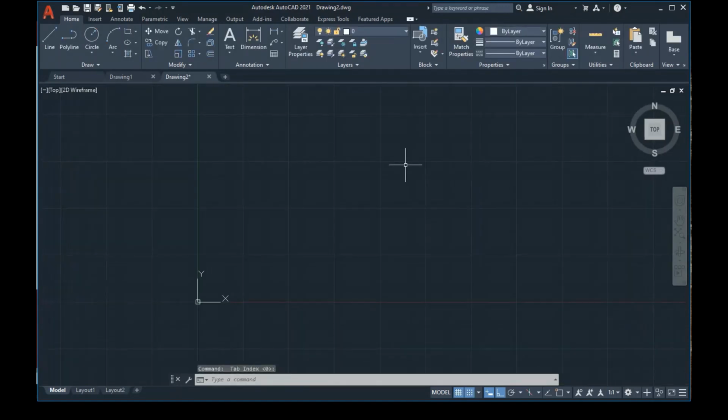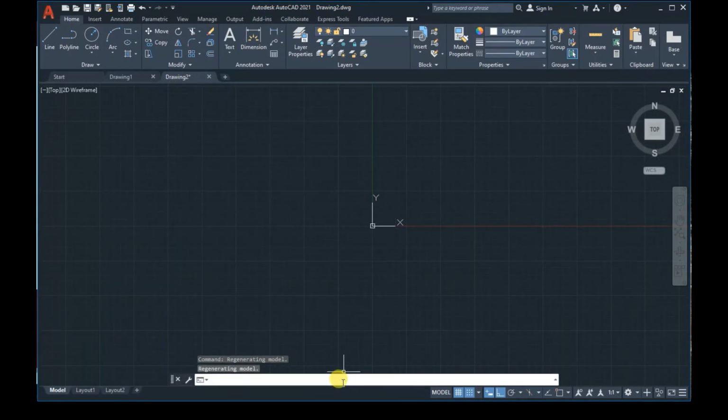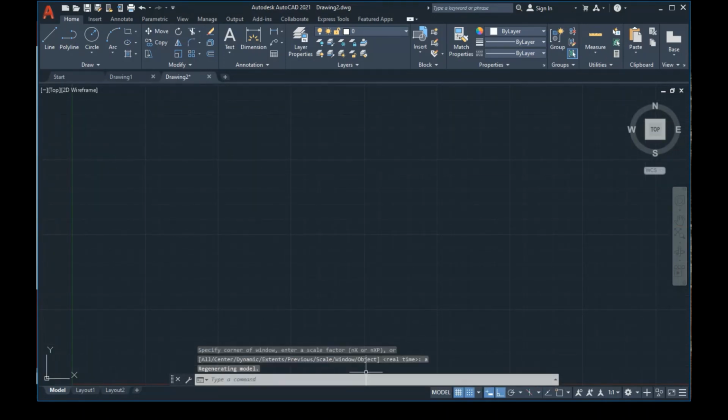Look, you can see these grid lines, and with every 5 lines, 1, 2, 3, 4, 5, there's a major line. So these are called grid lines. This helps you understand how to draw. Look, I have changed the settings. Now where will my screen go? I'll say Z, space, A, and enter. Now it is perfectly set into your screen. So the entire area has been zoomed like this. So this is the way to set up a drawing. We have set up the drawing.